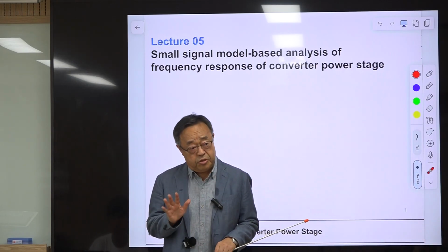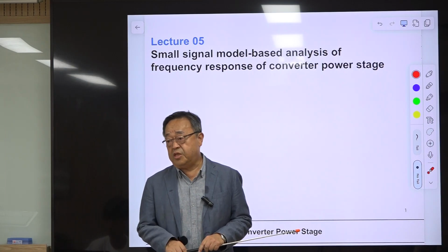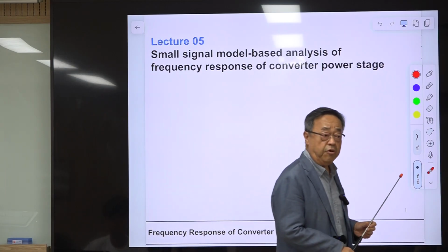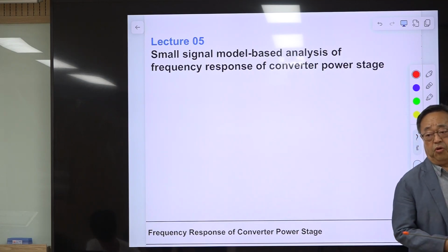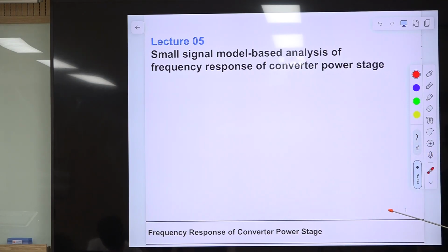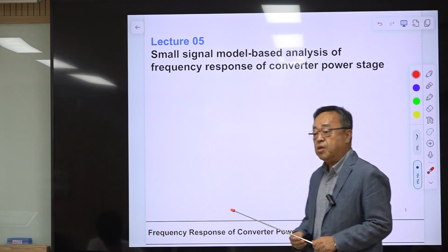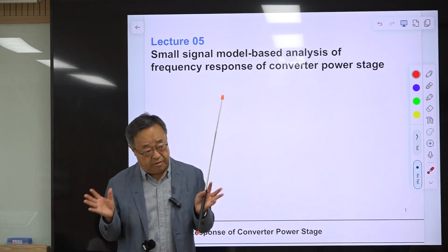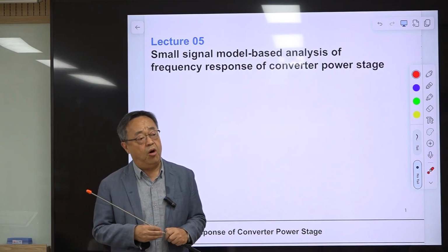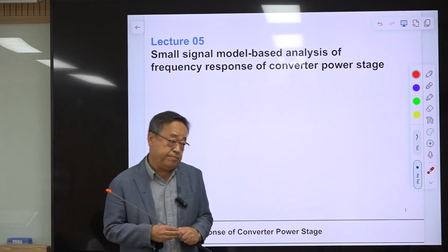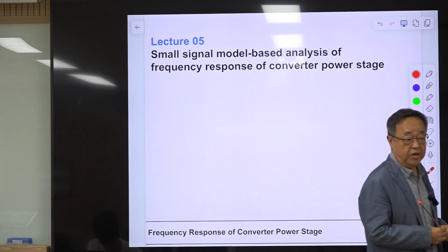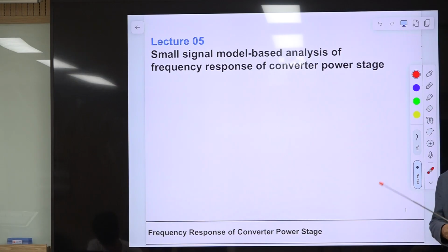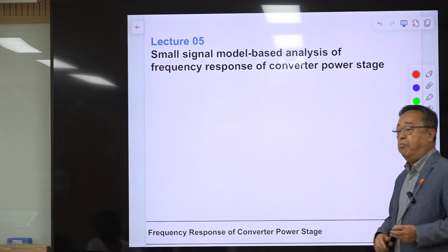We went through 4 lectures, and most of them we discussed the structure of the offline converter and the operation of the power stage of the flyback topology, and some bias circuit and the compensation structure of the feedback circuit composed of an optocoupler and an operational transconductance amplifier. Those stories are kind of steady state circuit analysis, okay? But for the remaining part, we need to go to some dynamics and control of this flyback converter.